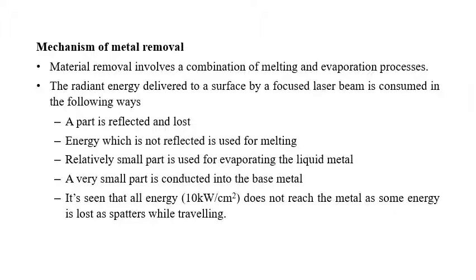A very small part is conducted into the base metal, and it is seen that of all the energy, that is 10 kilowatt per centimeter square, not all reaches the metal, as some energy is lost as spatters while traveling. So the energy of the laser beam is around 10 kilowatt per centimeter square, out of which some amount of energy is lost due to various reasons.